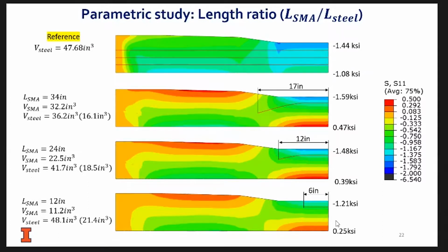This ratio plays a big role. The longer the fuse, the more pre-stress force we get. And that's expected. We have a longer fuse, it has more deformation, it can pull more of the steel, produce higher pre-stress force. And you see there, right there, the reduction in the steel, significant reduction in the steel with using this that could actually exceed 50%.